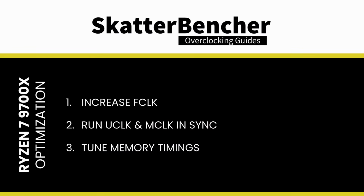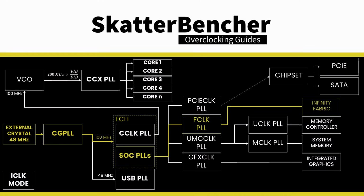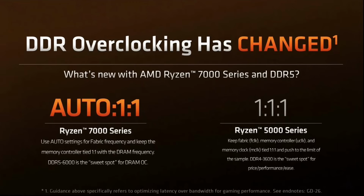There were 3 things I wanted to address with the memory subsystem performance optimization. I want to increase the F-clock as high as possible, I want to run the U-clock and M-clock in sync, and I want to tighten up the memory timings. The fabric frequency, or F-clock, is generated by the SoC PLL, derived from a 100 MHz reference clock input. The reference clock is multiplied by the F-clock ratio, which you can configure in the BIOS. While it can run independently from any other clock domain, it is still suggested that running the fabric clock in sync with the system memory and memory controller frequency provides the optimal performance point.